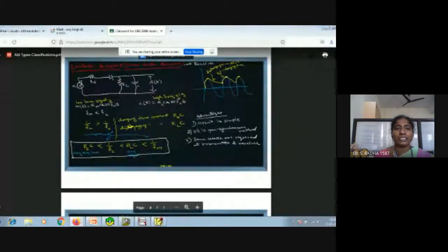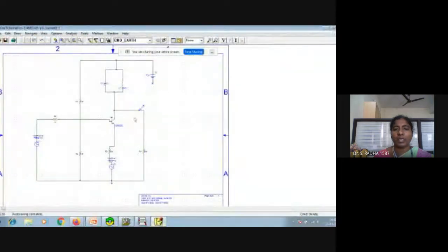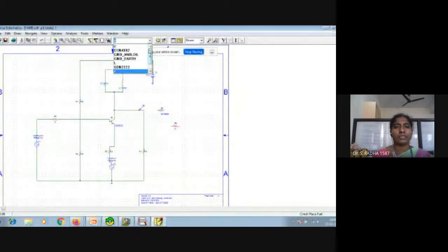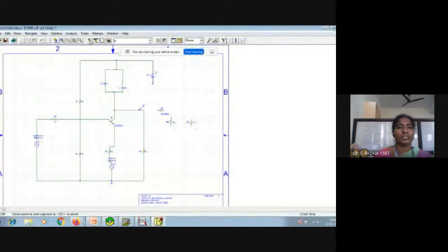Okay. So this VI is nothing but the modulated waveform. At this point we are getting the modulated waveform. So from here I have to connect the envelope detector, for which I need one diode, one resistor, one capacitor. Resistor, I will change it to vertical. Capacitor, both of them to be parallel. Select the resistor, Ctrl R, it becomes vertical. Select the capacitor, Ctrl R.